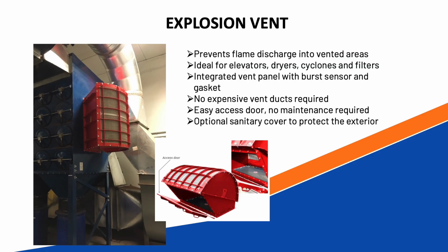When it comes to explosion venting, we have a variety of different solutions. If you have an indoor application where you need venting on your collector or your vessel, we can offer a flameless vent that goes on top of the explosion vent. And basically, what happens is, in the event of combustion or deflagration, the vent will open, which will relieve the pressure, and then the fireball will be quenched by the flameless mesh that you see on top of the flameless vent.